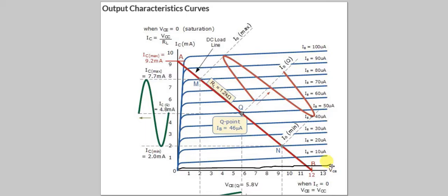This is due to the minority charge carriers, and the ultimate job of the engineer or the scientist, when producing the transistor you are making, is to keep this region as low as possible. So this is because of the minority charge carriers, unwanted, uninvited charge carriers, as you know, due to temperature or various other factors, we might have the heating effect inside, or excessive current flowing through